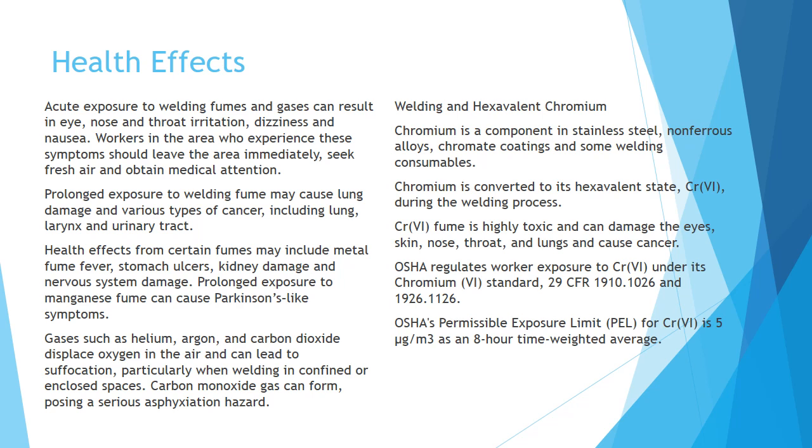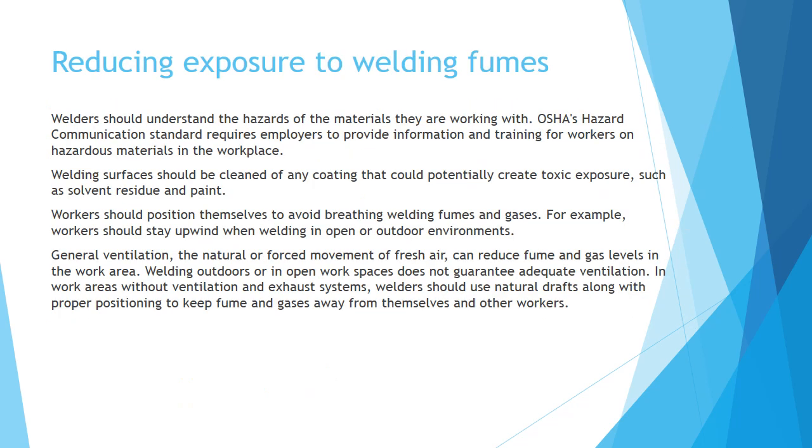OSHA regulates worker exposure to chromium 6 under its chromium 6 standard, 29 CFR 1910.1026 and 1926.1126. OSHA's permissible exposure limit, or PEL, for chromium 6 is 5 micrograms per cubic meter as an 8-hour time-weighted average. Reducing exposure to welding fumes.